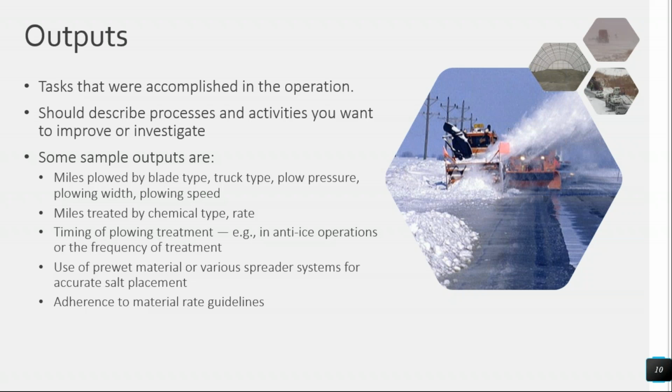You can also do the same thing with miles treated. Well, treated how? By which chemical and what rate? You can talk about maybe the timing of how they do their treatment. So whether people do anti-icing operations or whether people in your agency tend to do a very frequent treatment versus a hit it hard and then leave it for a while kind of a maintenance philosophy.